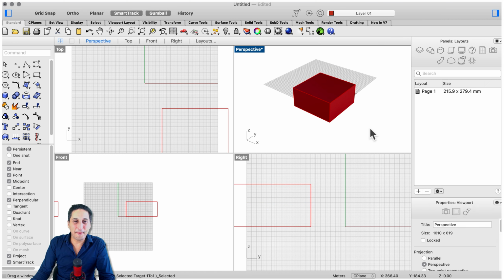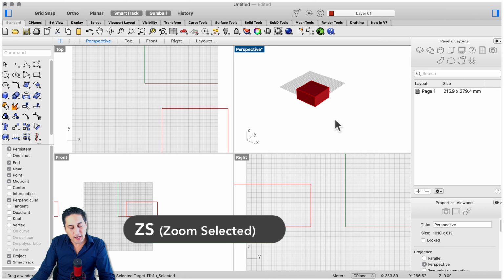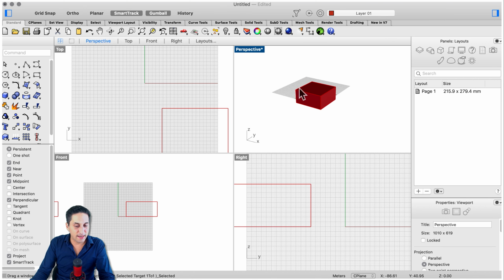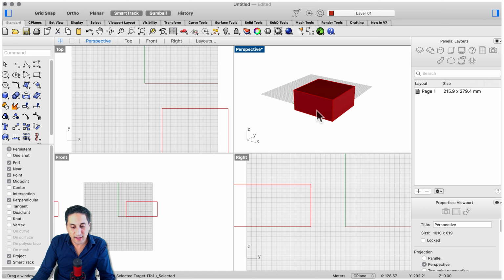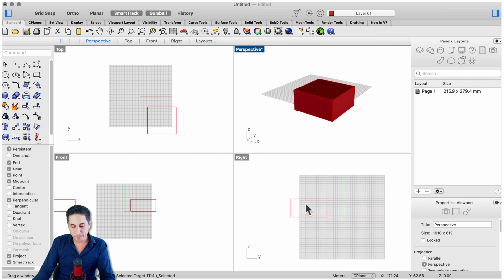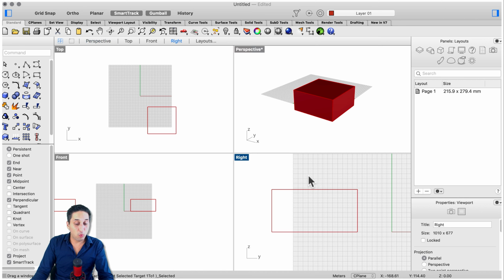Let's keep going. Next up is the display mode. Now, as you can see here, this has a specific name to it, which is called shaded. It means that I have a solid that is being shaded in OpenGL so that I can see its volumetrics and have different shades depending on the side for my eye to understand that there is an edge between them, right? But there are actually many ways that Rhino can show you this information. On the right and top view, this is all being set up as wireframe, meaning that we can only see the lines of the object. We can interchange this and even have more different ones, as I'm going to show you right now.